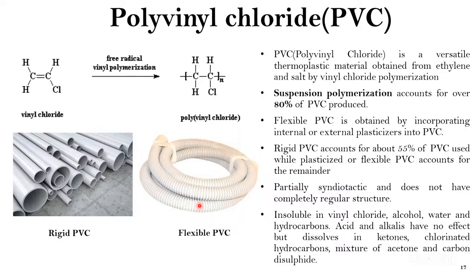I think thermal resistance also, right? Yes, thermal resistance. Opposite to this, if PVC can get dissolved in these, which material will not dissolve? If I want to transport a ketone or acetone, you can keep it in a PP bottle, polypropylene.